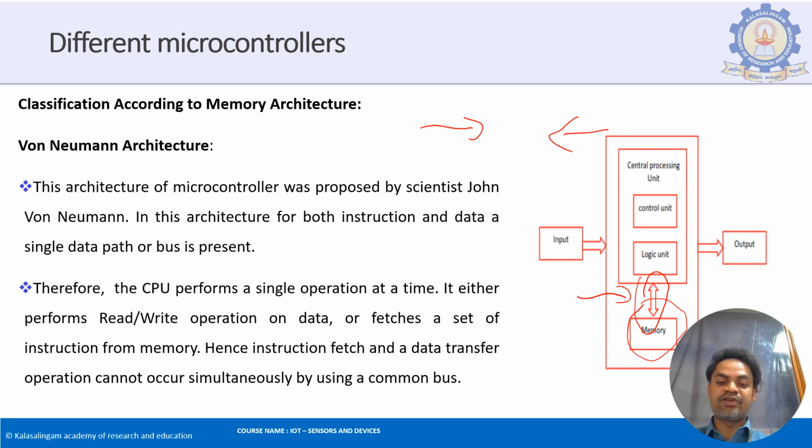But here, one after the other, you can only take care of them. So that is the von Neumann architecture. Two different architectures, each having their advantages. What is the advantage of the Harvard architecture over here? You are saving time. You can move the data separately. But the drawback is it takes a lot of space. You have separate buses over here, one used for instructions, one used for data.